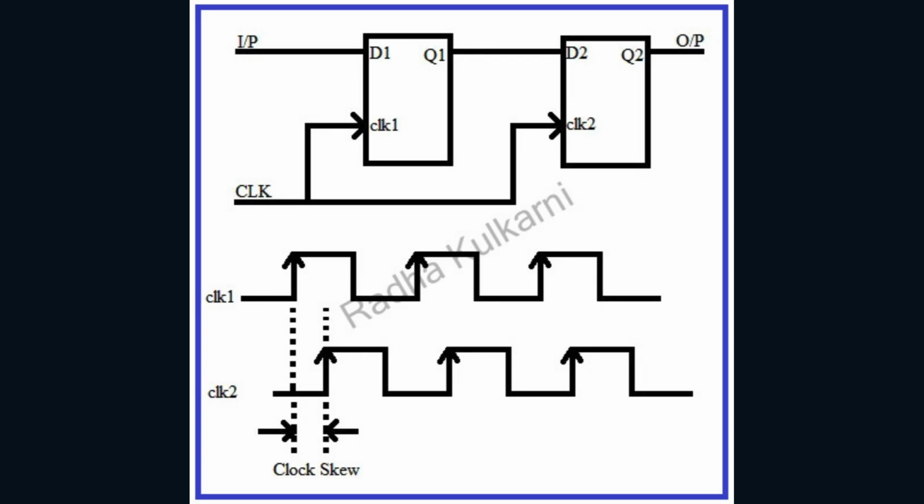The clock might hit flip-flop A at time t, but it might reach flip-flop B just a tiny bit later, say at time t plus n. That little difference, could be picoseconds, maybe nanoseconds, that is your clock skew. It's just a consequence of physics sending signals across a complex surface. Right, I see. So the actual layout matters, how long those tiny wires are, maybe even what they're made of. It's fighting these tiny, tiny differences. Wow. Okay, that sounds like it could be chaos across a whole chip.